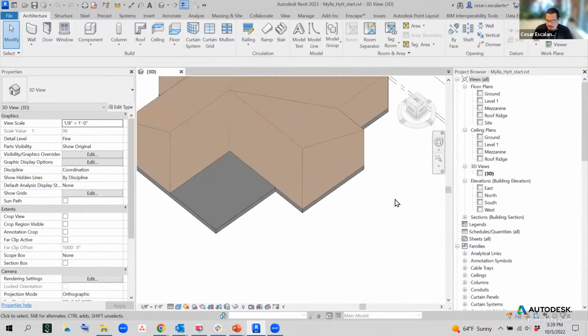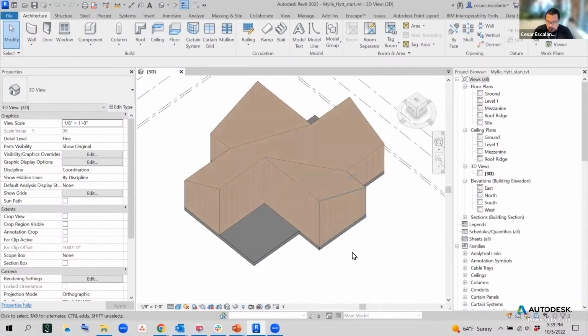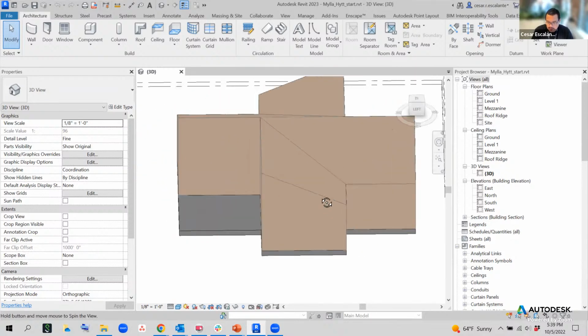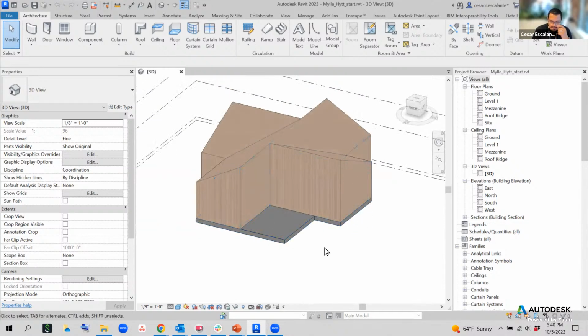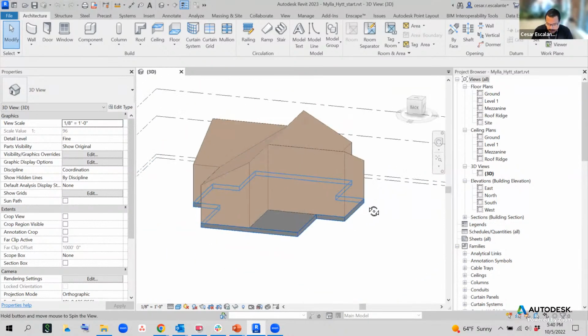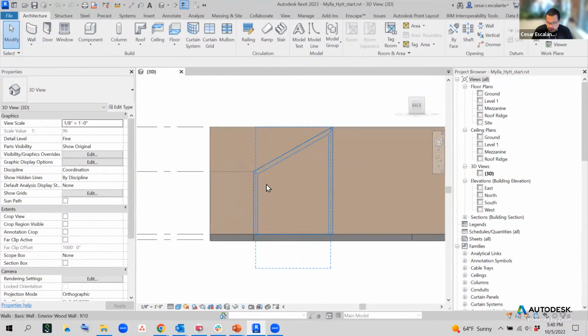What we're gonna do today is we're gonna place doors, we're gonna place windows, and we're gonna place curtain walls. I think as you can tell from the 3D view here, the geometry has come very clean as a result of using the appropriate wall connections. If you recall, these walls are mitered at a corner.